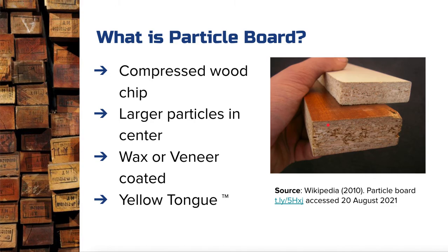But if you've got chipboard and it's a little bit old, you would know that it starts to expand over time. If the surface has been damaged and water has gotten in, then it really expands to a much larger size. So really susceptible to water damage there, but again, quite cheap. Particle board is really heavy. So if I'm thinking about my experience working with this, I find that this is probably the heaviest of the three materials to work with, because you're working with wood chips, and even though plywood should technically be heavier, the particle board is deceptively heavy for its size.